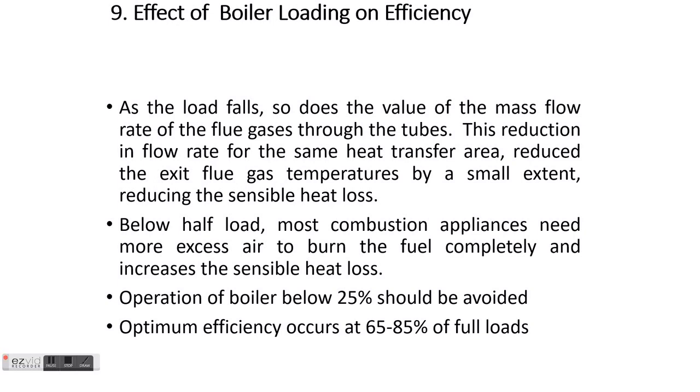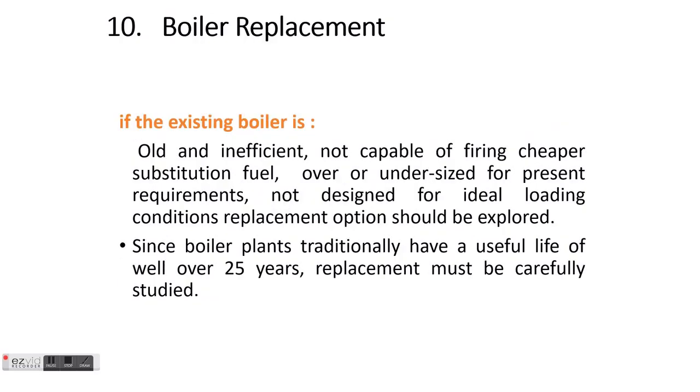Below half load, most combustion appliances need more excess air to burn the fuel completely. This increases the sensible heat loss. In general, efficiency of the boiler reduces significantly below 25% of the rated load, and as far as possible, operation of boilers below this level should be avoided.